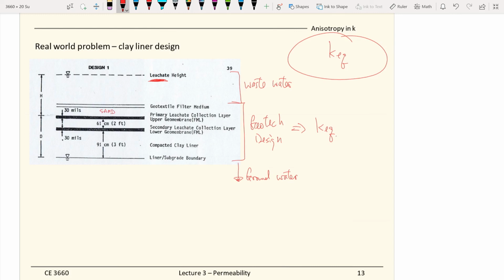and then on top of that a very thin layer, what we call the geomembrane, which is pretty much a plastic layer. The thickness of this layer given to you is 30 mil, and 30 mils is in fact equal to 0.0762 centimeters. So it's a very, very thin layer. It's kind of like a plastic layer that you can wrap around the soil.